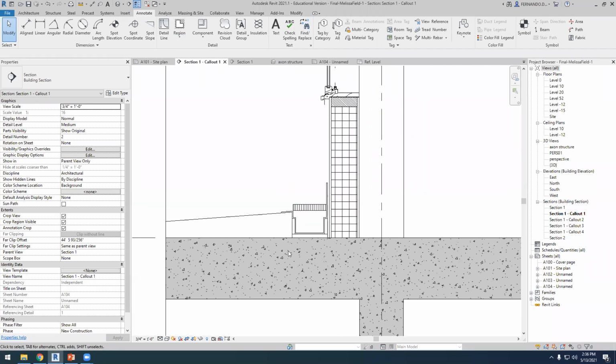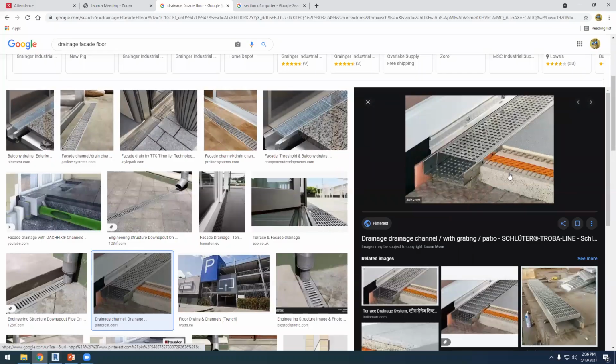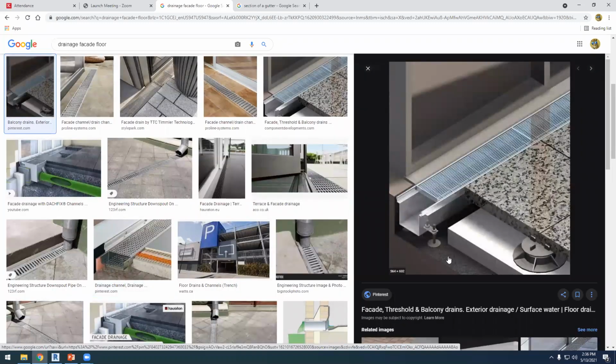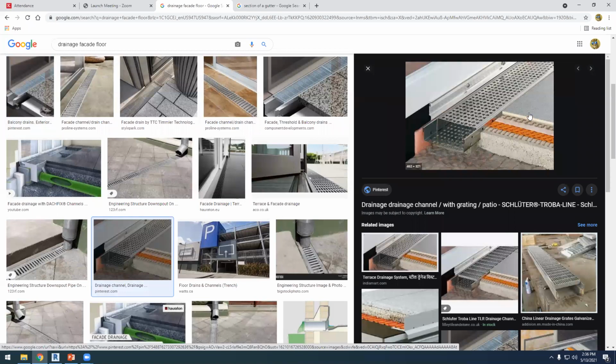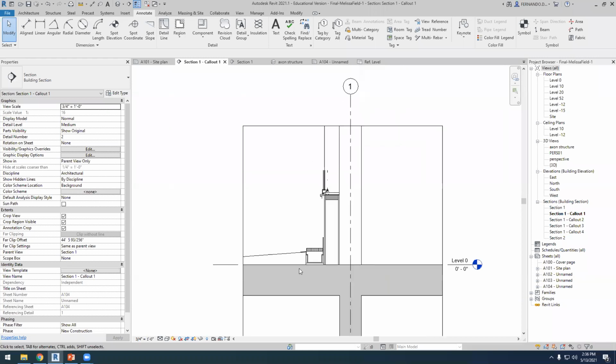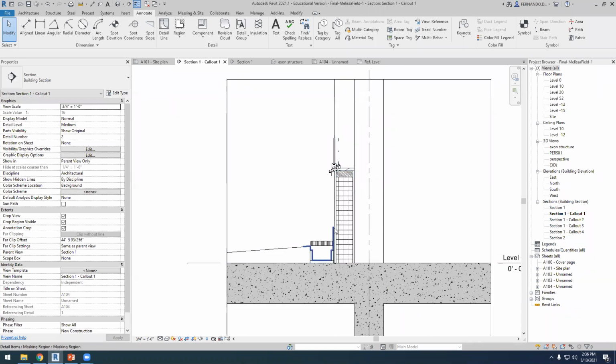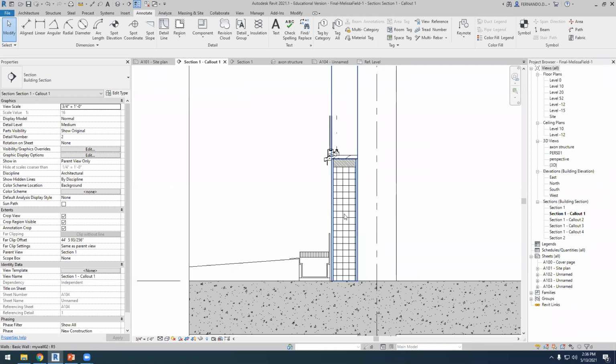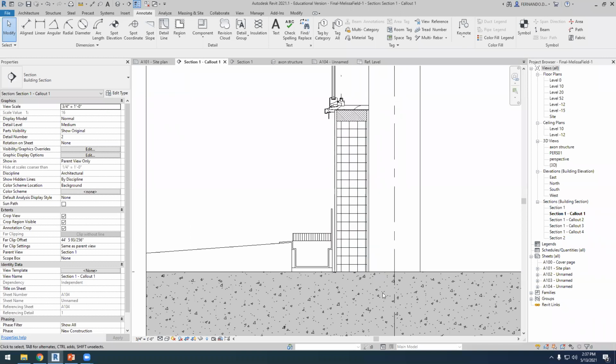But now we can't work without the waterproofing. You see that here we have different waterproofing layers, or here we have this black stuff, okay? So where do we have to place the waterproof layer? Just underneath this flooring here, or underneath the gutter? So I would say both, in both places. And then I need to wrap this wall so that the water doesn't affect the wood, because this wall is made of wood. Okay, so we have to be careful with this wall.